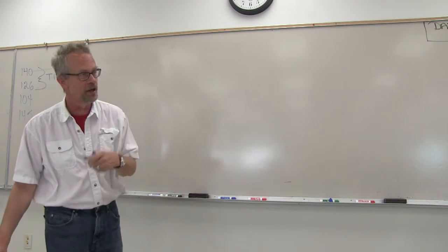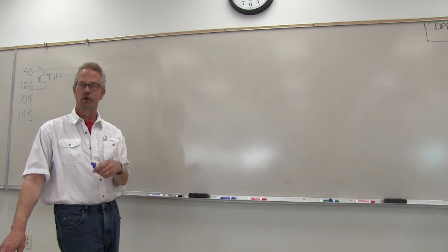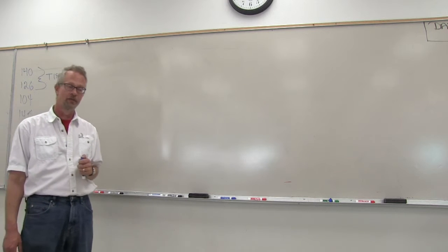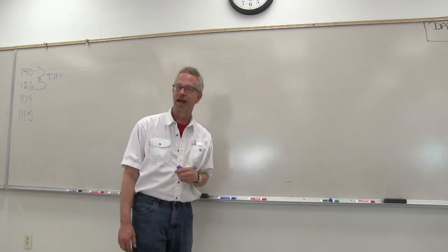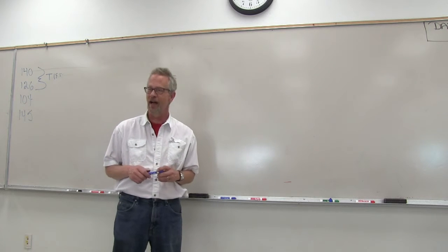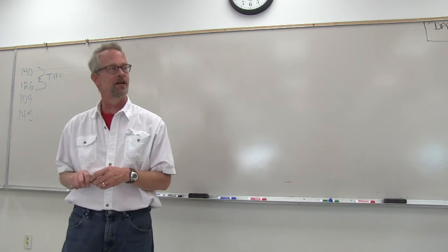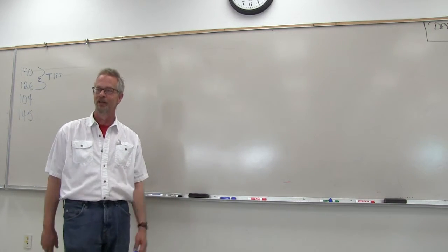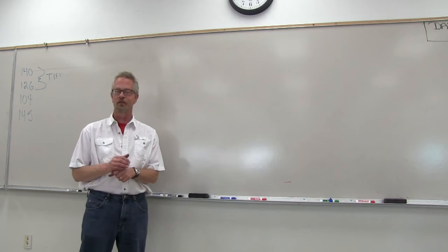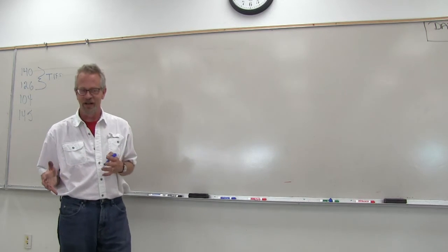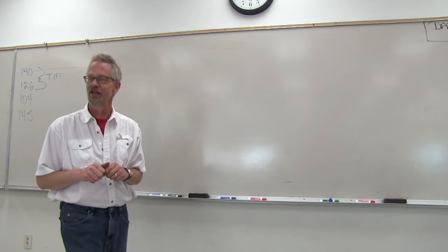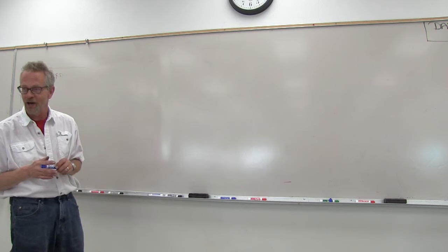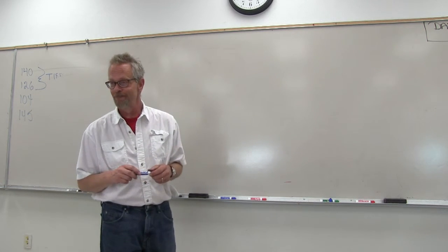If you look over there, you'll notice that the fuse panel that's on those boards has a lock on it. Can you see the red lock that's on there? Yes, sir. We're going to spend most of the day on Monday talking about that as a process. It's called lockout tagout. It's a way to make sure that somebody doesn't inadvertently come over and turn that on while you've got your hands in stuff. So all that stuff is a process, there's a procedure, there's an industry standard that we have to discuss relating to how we keep safe when we're working on higher voltage, higher potential sources.